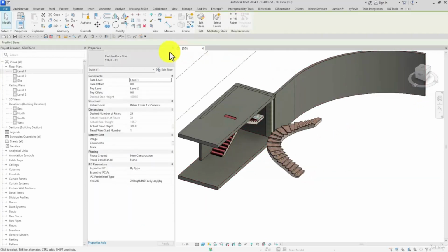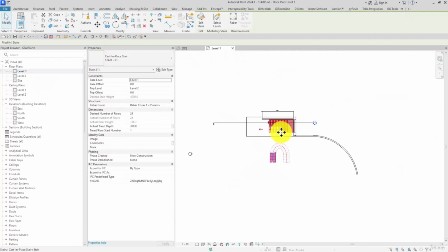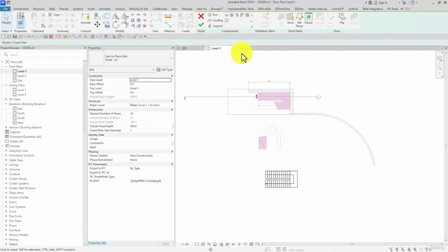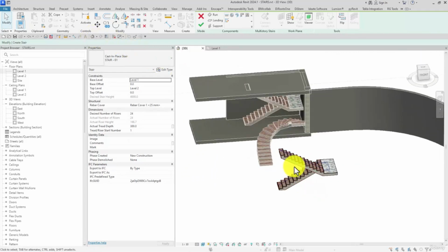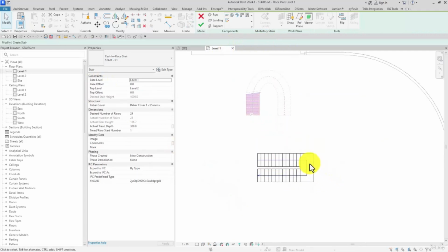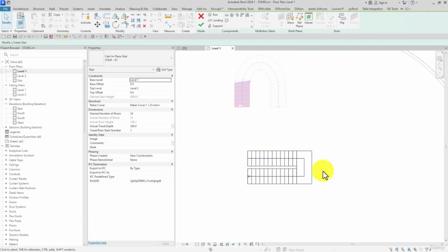And if we create a stair using components like these, this time if I open the sketch stairs, as you can see, edit a sketch is not available for it since this is not a sketch, this is a component. So as you remember, we can edit the components from their parameters as we talked about them. But if you wanted to convert the stairs that were created by component, you can use convert to sketch based.